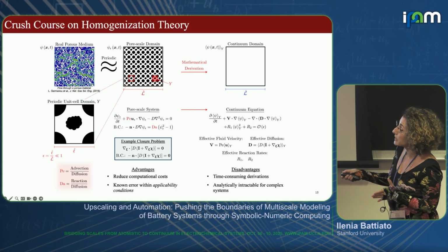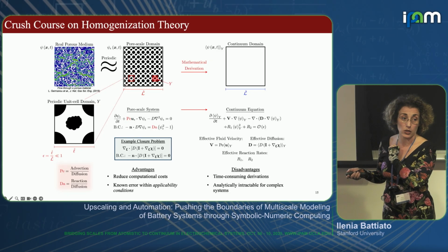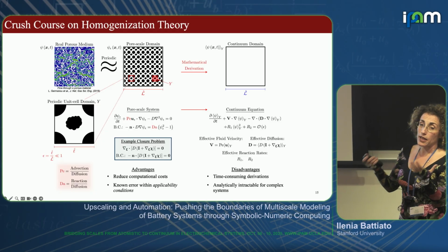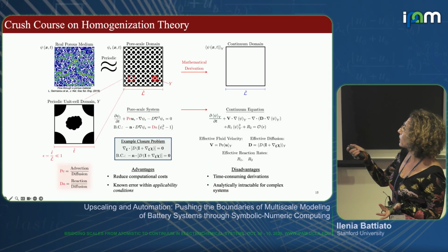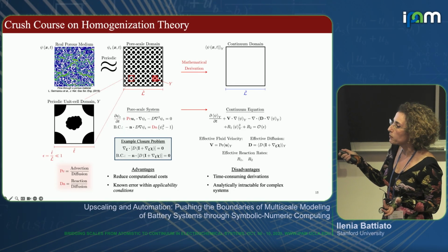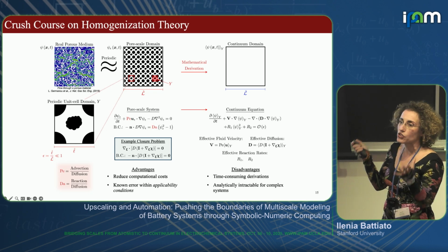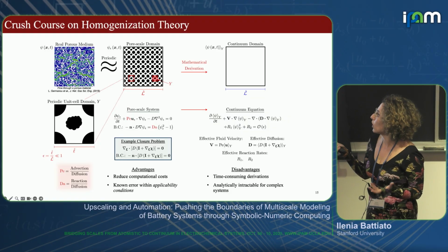Now, the size of this unit cell is small l, and the ratio between small l and big L is epsilon. This is called the separation of scale parameter and must be much, much smaller than 1. So what homogenization does effectively is the same effect as looking at this picture and squinting your eyes, right? If you squint your eyes, essentially you won't be able to see these things anymore. You will see just a homogeneous, possibly gray continuum, and that's the limit where we're going to work.